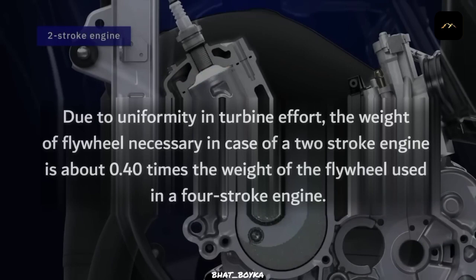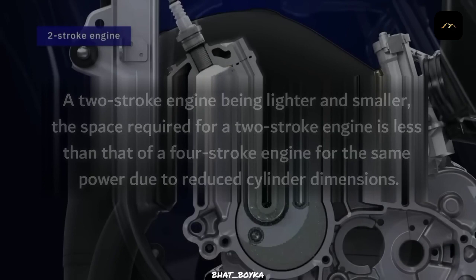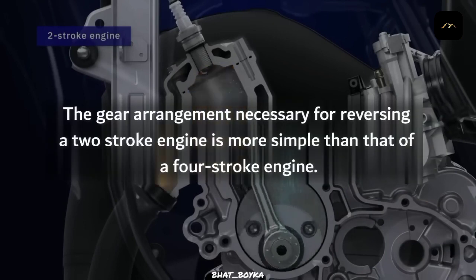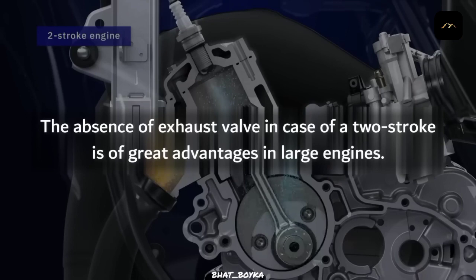Due to uniformity in turning effort, a lighter flywheel is necessary in case of a two-stroke. It is about 0.40 times the weight of the flywheel used in a four-stroke engine. A two-stroke engine, being lighter and smaller, takes less space than a four-stroke engine for the same power due to reduced cylinder dimensions. The cylinder temperature in a two-stroke is higher than that of a four-stroke engine. The gear arrangement necessary for reversing a two-stroke engine is simpler than that of a four-stroke engine. The absence of an exhaust valve in a two-stroke engine is of great advantage in large engines.